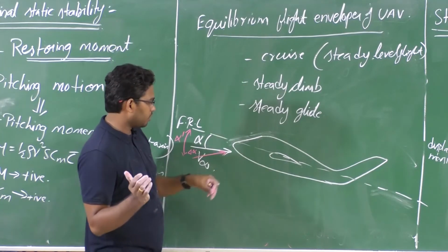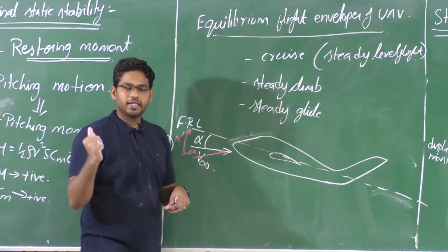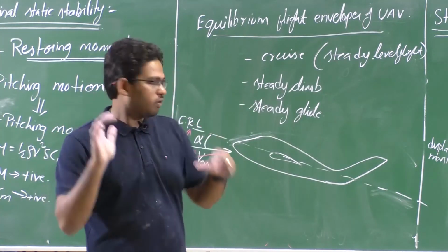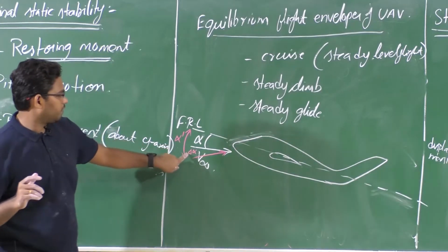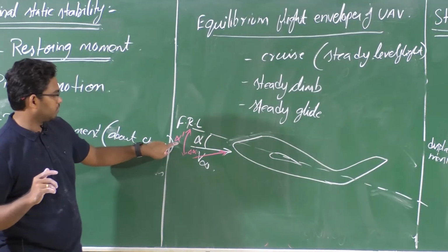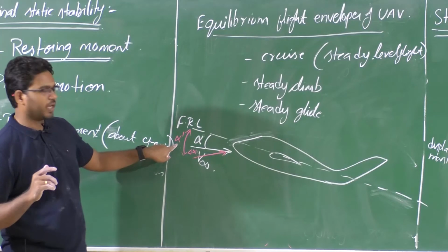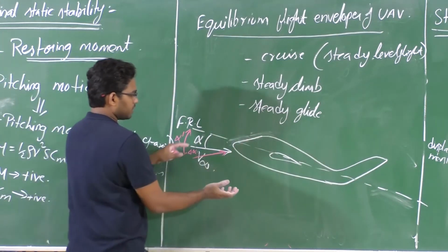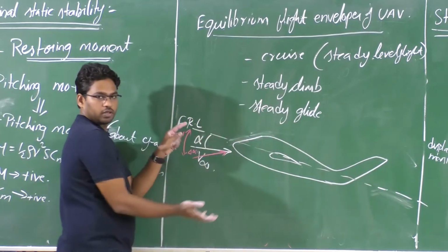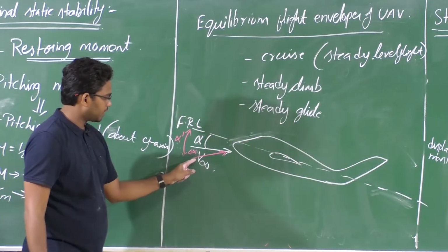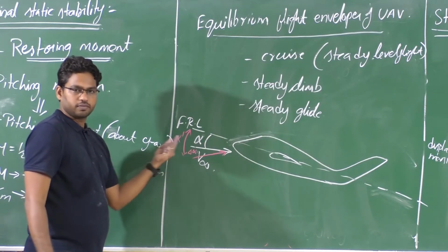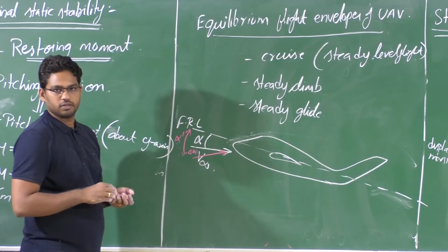If this aircraft can rotate in such a way that the increased angle of attack is nullified, say now we have the change in angle of attack nullified, so the aircraft now sees a new angle of attack, alpha prime. If I rotate this aircraft pitch down, a nose down moment, then I can reduce this alpha prime to alpha by nullifying this delta alpha, right?